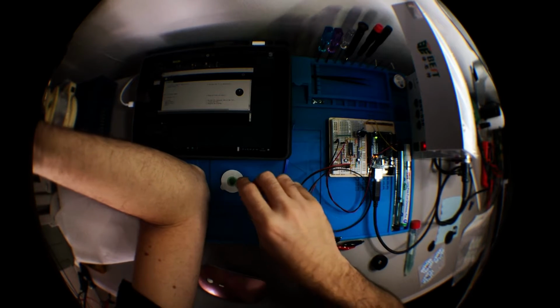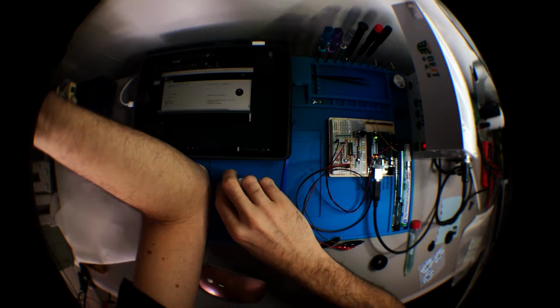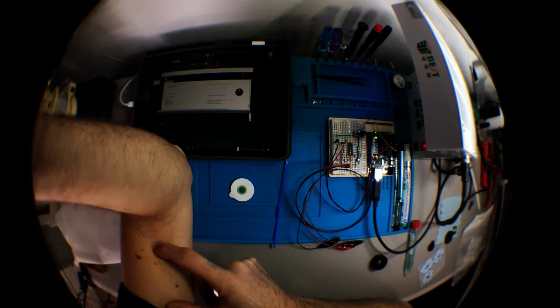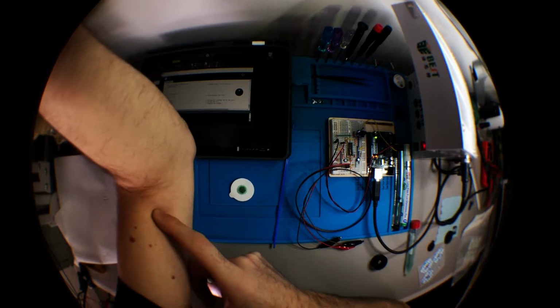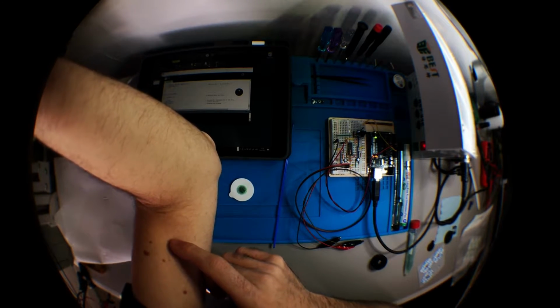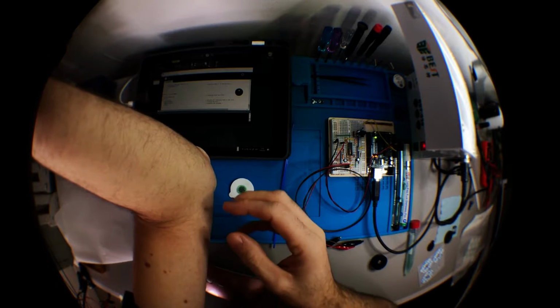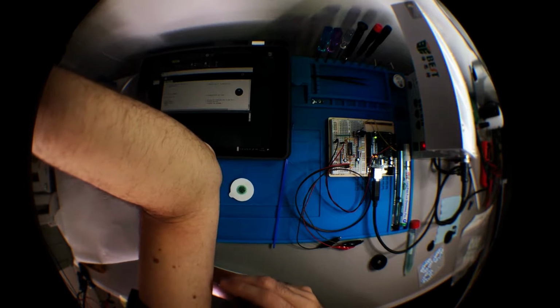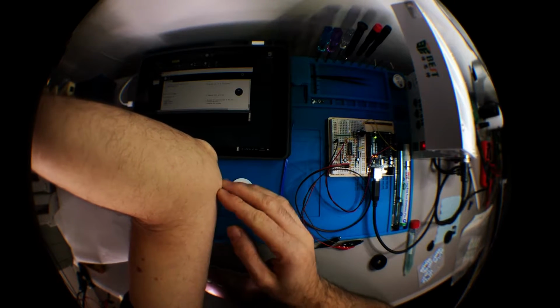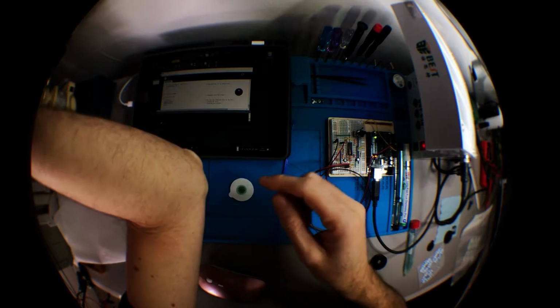So the idea is to attach one electrode at the beginning and one at the end of the muscle. So you have a maximum voltage displacement. And the reference into a place where you don't have a muscle. But it's difficult because the human body is fully covered of muscles. There are a few places where you have no muscles. One is this one, for instance, close to this bone here.